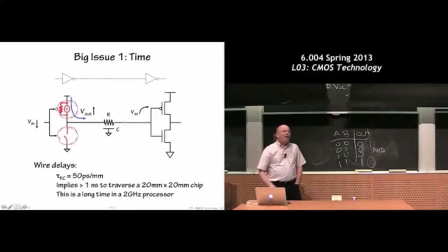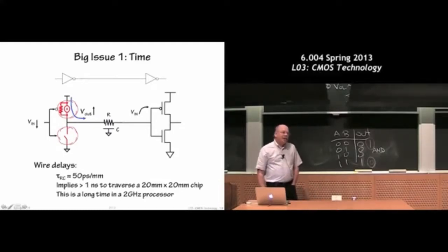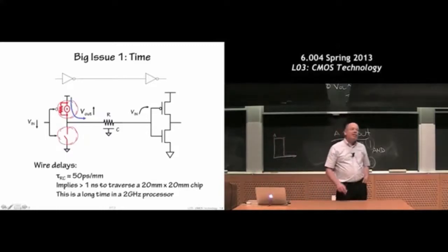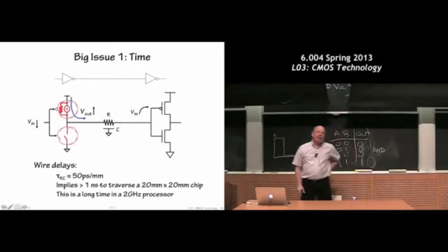Getting signals to go across the network and to change out of one of the logic gates might take on the order of tens of picoseconds, and then basically transmitting the signal down the wire. You can see it takes about 50 picoseconds per millimeter. In other words, the speed of light along these conductors embedded inside these insulating dielectrics is not quite the speed of light.